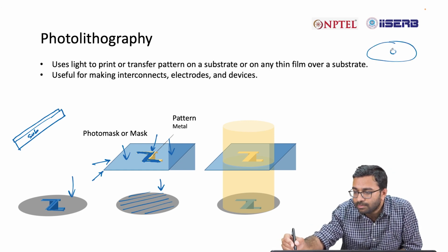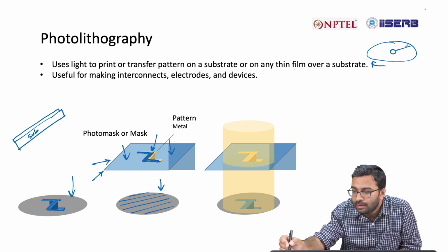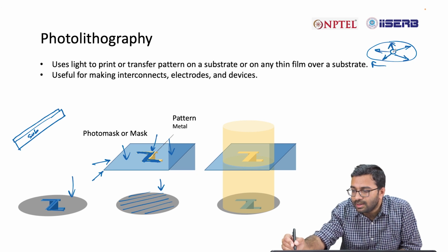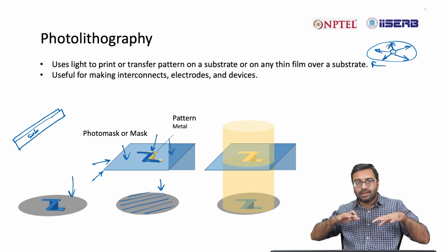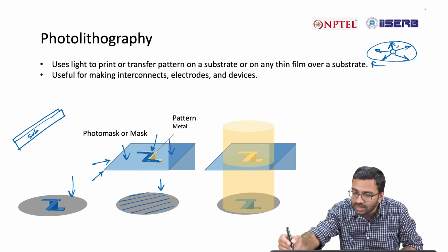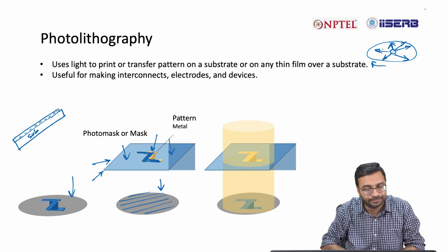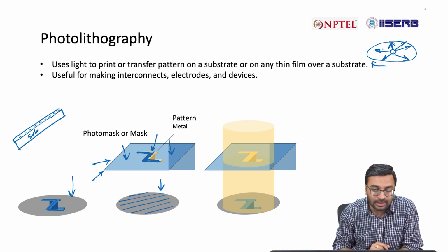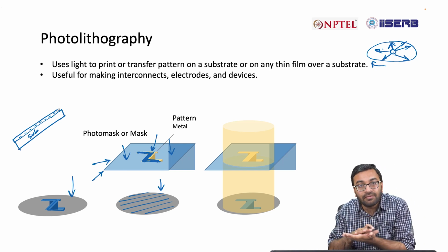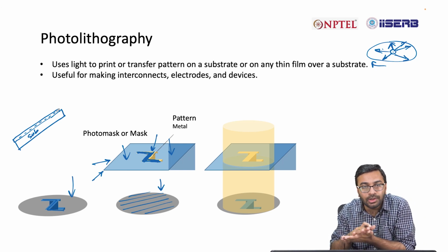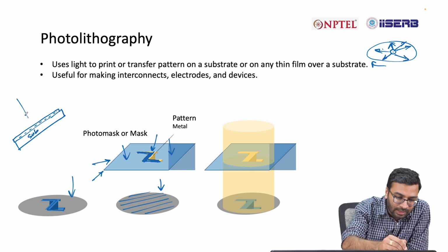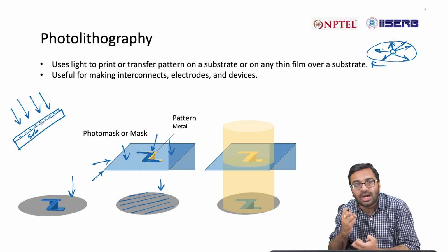Once the material is placed on this, say, circular substrate, and once you start spinning, because of the centrifugal or centripetal force, this material will start spreading on top of that substrate, and when it starts spreading, it will create a thin film like this. I hope you can visualize. Once this is created, now your substrate has a thin film of that polymer. Now, the property of the polymer is, if light interacts with it, say the polymer hardens.